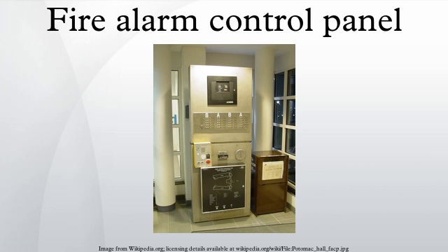Pre-alarm. This LED is often used in conjunction with a two-stage system, in which the panel requires two devices to be activated in order to go into full alarm. This is mostly used in areas where false alarms are a common problem, or in large applications where evacuating the entire building would not be efficient. The pre-alarm LED is lit when one device has tripped. The pre-alarm LED may also be used if an analog smoke detector registers low levels of smoke in the detection chamber, but not enough to trigger a full alarm.